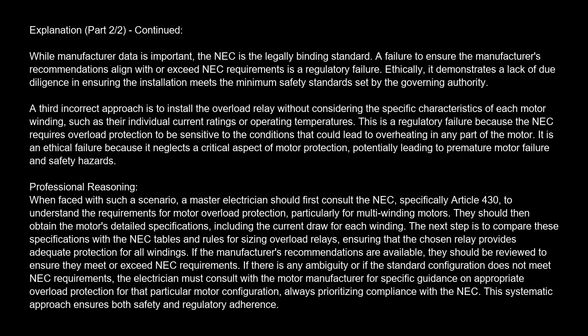If the manufacturer's recommendations are available, they should be reviewed to ensure they meet or exceed NEC requirements. If there is any ambiguity, or if the standard configuration does not meet NEC requirements, the electrician must consult with the motor manufacturer for specific guidance on appropriate overload protection for that particular motor configuration, always prioritizing compliance with the NEC. This systematic approach ensures both safety and regulatory adherence.